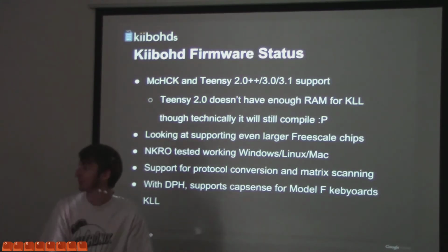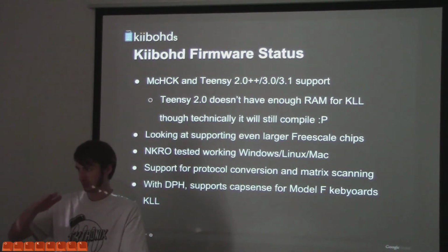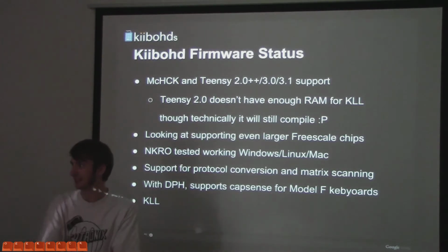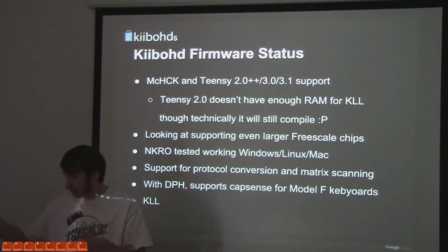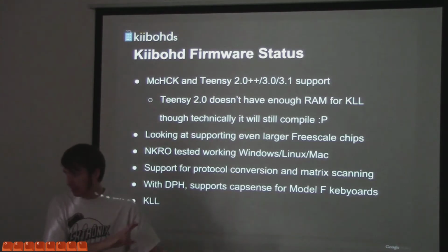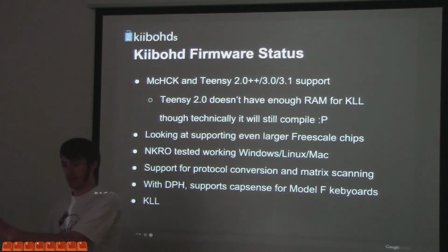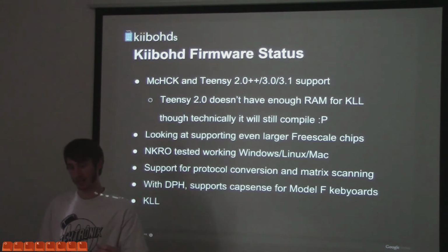Now there are issues with doing this. A switch doesn't completely close 100% immediately. There are laws of nature we have to deal with. Debouncing: some part of it has to control debouncing. That was originally done on the computer, but to simplify work for the computer so it could do other more interesting things, they tried to offload that onto the keyboard. So it would do debouncing, sometimes even holding, press, release, so it would just send the characters that it needed. It would be a full-on terminal, that sort of thing.